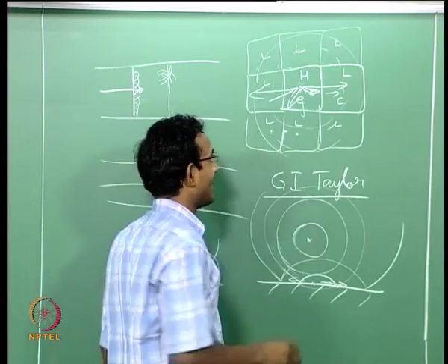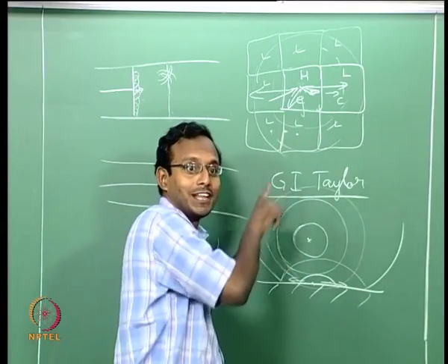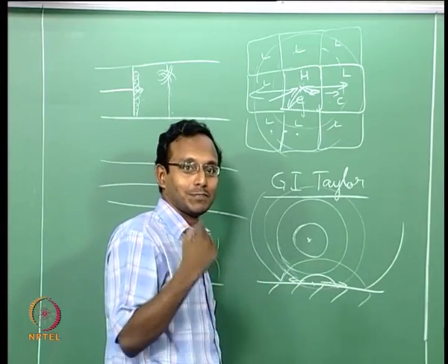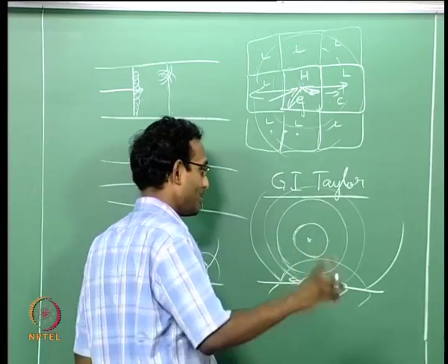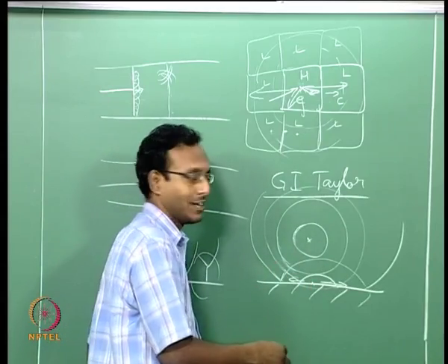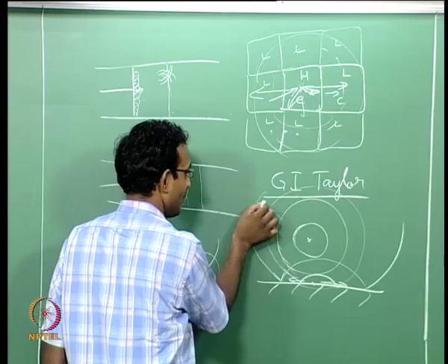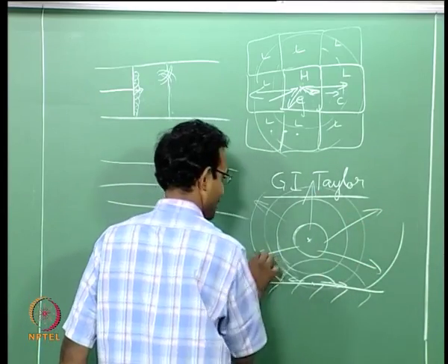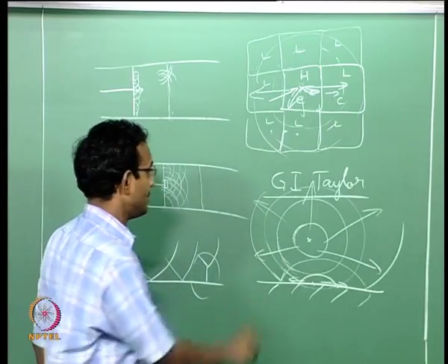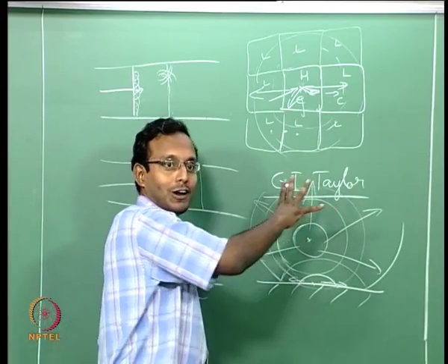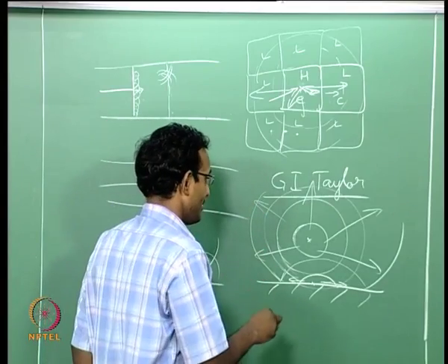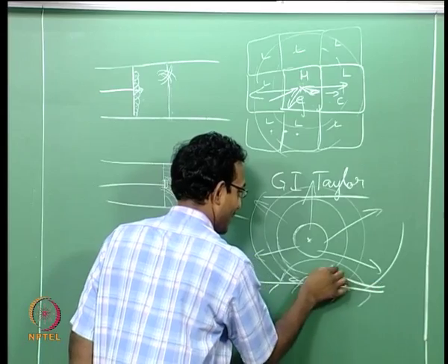Those expansion waves, what will they do? They will induce flow in the opposite direction. "Oh, that place is too empty, now go back the other direction." That is what the expansion waves are now telling, and that is what is causing the reverse flow. Until this point, all fluid elements were going out in all directions. This is just going to create some big cloud of exploding gas, but after some time suddenly fluid wants to enter.